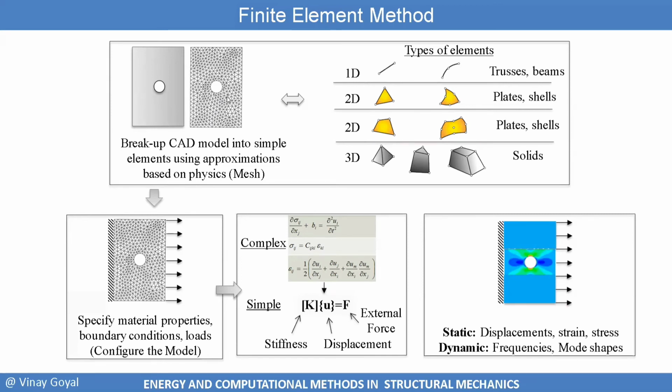The elements we choose could be 1D, 2D, 3D, tetrahedron, solid elements, hexahedral elements, plates, shells, beams, trusses. We're trying to simplify, idealize a structure into something simpler in which we can solve these equations. If I can solve the equations on one triangle, say, and it could also be quadrilaterals, perhaps I can solve it for every single triangle and then connect the solution somehow.